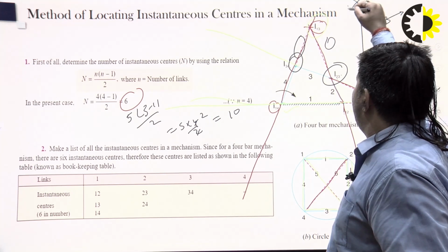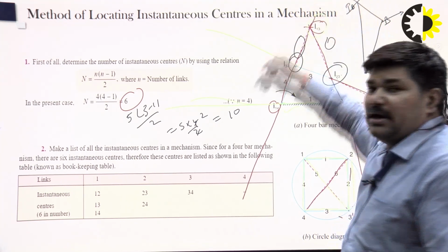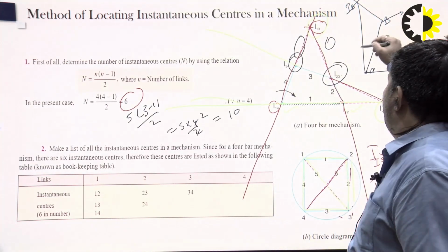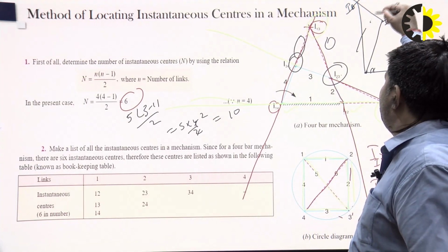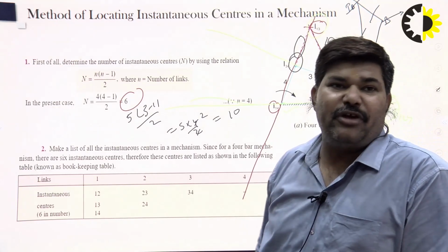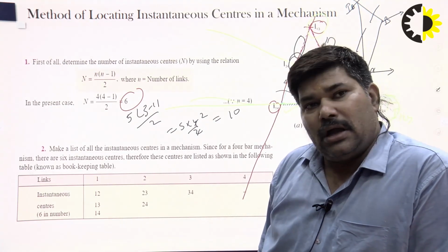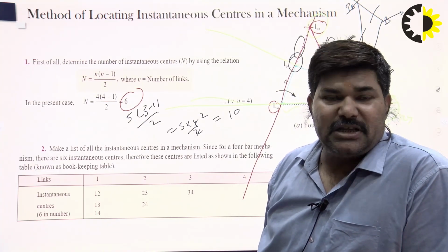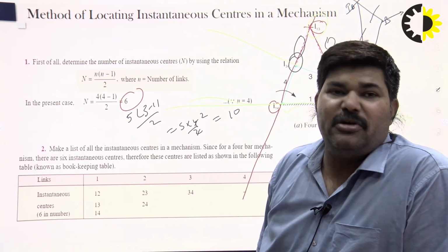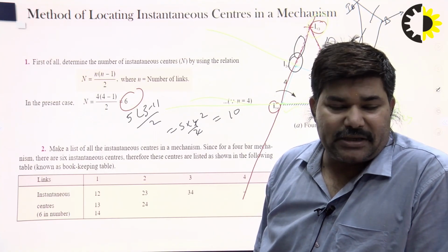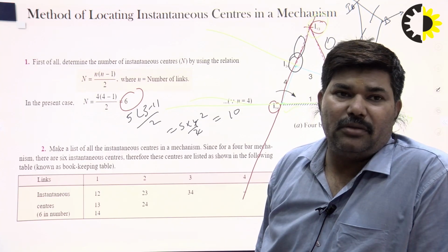Where they meet, that point is the instantaneous center, and then you can measure this distance and find the magnitude of point B. Using this, the angular velocity of the link AB is constant, that is omega, so omega is common. So the velocity direction of point B is already known, so you can find out the magnitude, right?